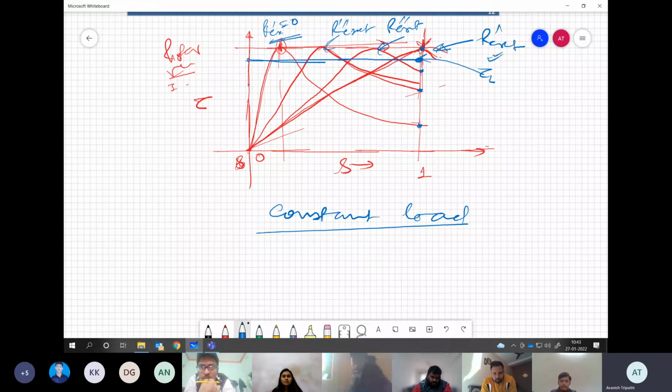Then the speed improves. Now the operating point, if you don't change the resistance, will be here. This is where the load torque and the electromagnetic torque are intersecting. So it will be operating at this point. Now if you cut down the resistance, what will happen? The characteristic or operating point will shift here. A better slip zone. This slip was very, very high. So the slip value will improve and the omega m will increase.